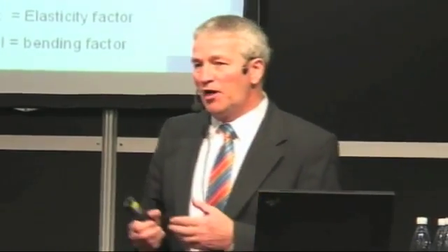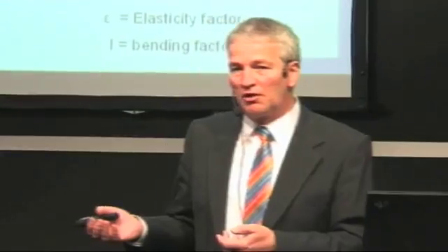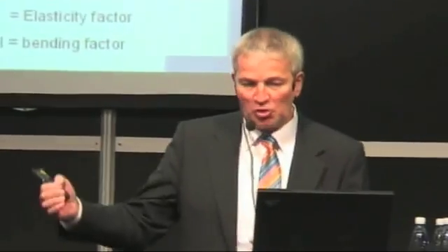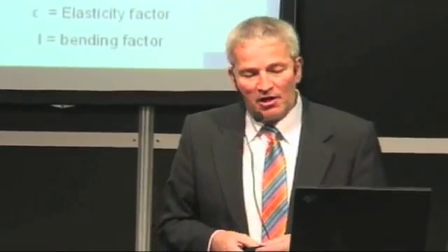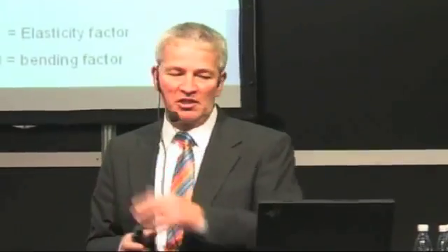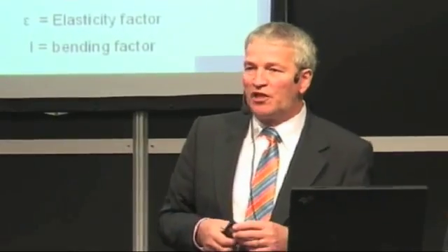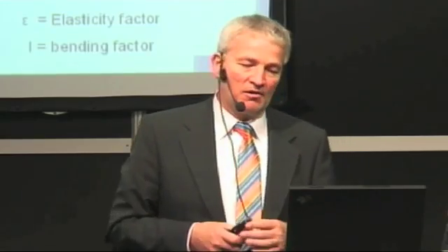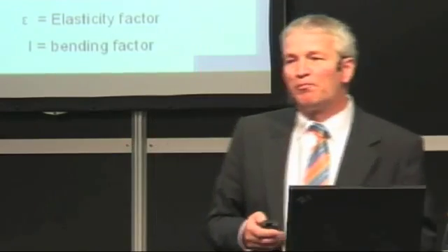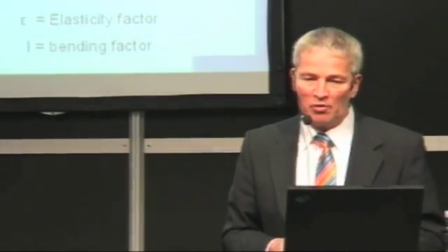First will be the self-weight of the tool. If the tool becomes heavy, it is also hanging down. Chip evacuation, cutting forces, feed forces, and so on are acting here on the drill. Basically, it is not a critical situation if the tool is deflecting to the side, but there are size variations, which directly influence the surface finish, and sometimes the whole drilling process will not be stable anymore.